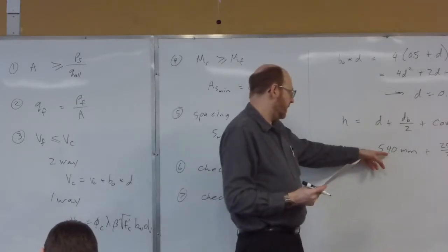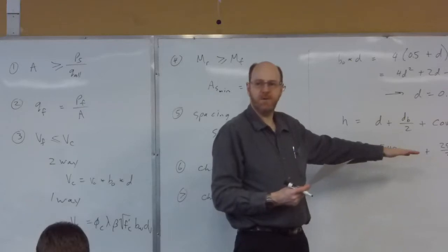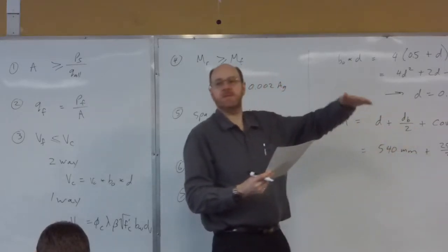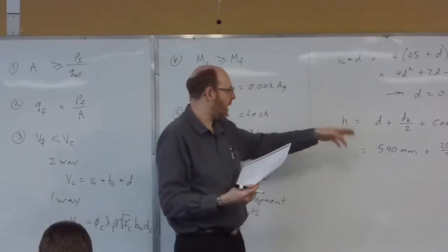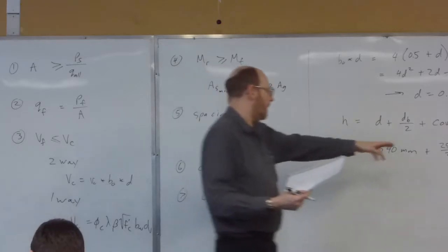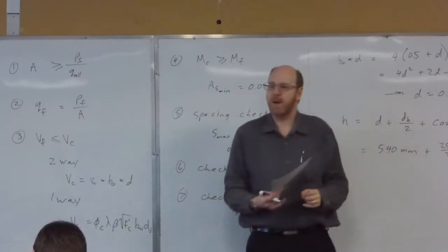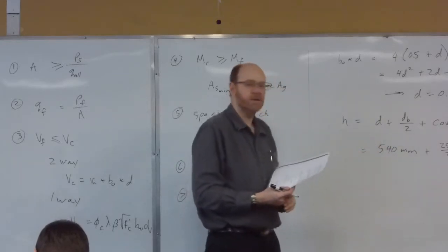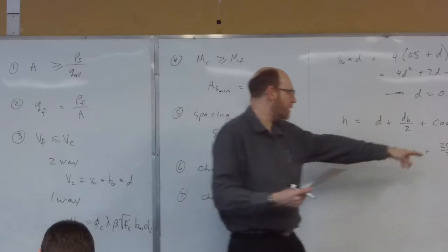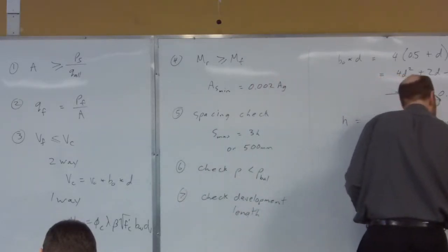What we've got here is the distance from the top down to that first row of reinforcing. Well, in the other direction, the bars are going to be slightly higher, by another 25 millimeters. So in our case, if we round this up to 650, we're pretty good. I'm not going to worry about that extra 3 millimeters, it's close enough. Remember, we've got some variation in there and a much higher cover distance here as well. So I'm going to use H of 650.